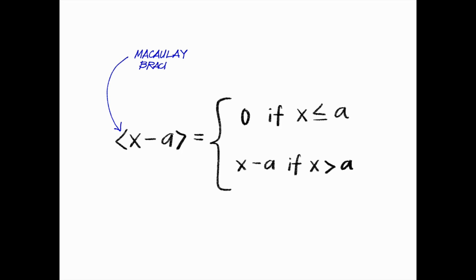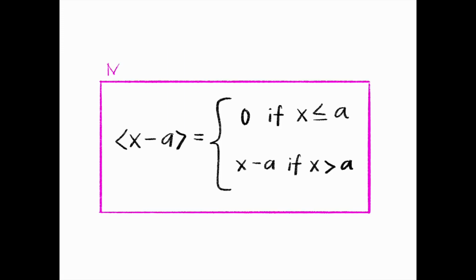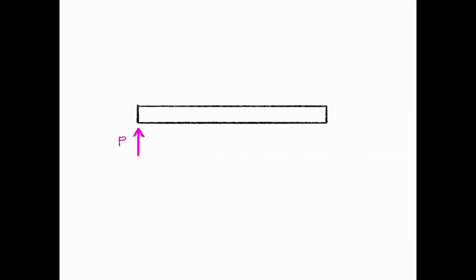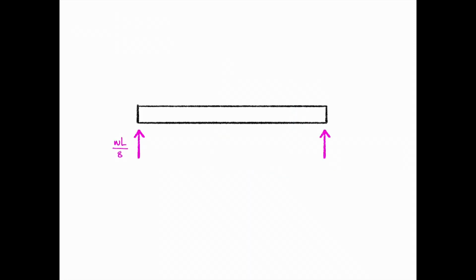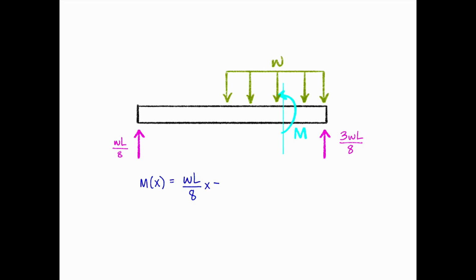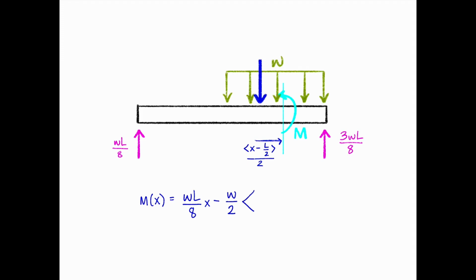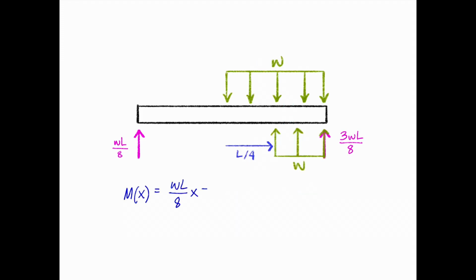These Macaulay brackets simplify the deflection calculations as they let us turn off different terms in the bending moment equation as we move along the beam. Let's apply this to our earlier cantilever beam example. With a single expression for M, we can directly apply the double integration method without sectioning the beam, although using Macaulay's method streamlines the process. The double integration method can still be time-consuming to implement.